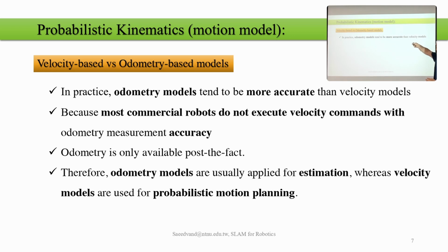In advanced SLAM algorithms, both can be used, and the velocity model is also very common to be engaged. For example, we will see later one advanced one, the basic concepts of ORB-SLAM, where you will see that we can have velocity models as input of the algorithm. Also, one important point is that in the Kalman filter we will also consider velocity models as input because it's easier to plug into the equation.